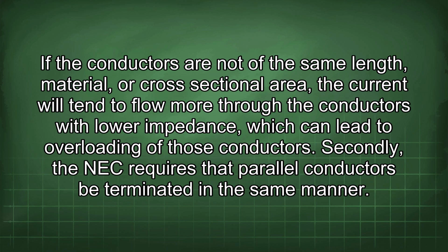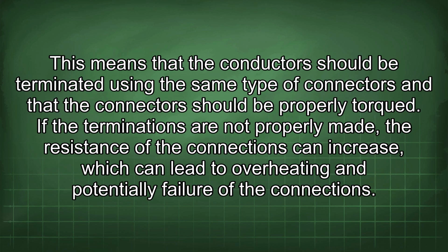Secondly, the NEC requires that parallel conductors be terminated in the same manner. This means that the conductors should be terminated using the same type of connectors and that the connectors should be properly torqued. If the terminations are not properly made, the resistance of the connections can increase, which can lead to overheating and potentially failure of the connections.